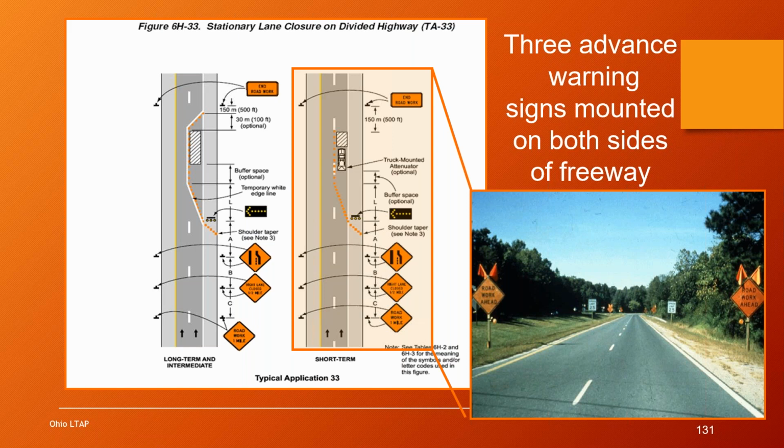roadway. And that's important in this situation because, well, one reason is you can think about heavy truck traffic. If a regular sized car is in the left lane and there's a whole string of semi trucks in the right lane, they may not see all the signs that are on the right side of the road. So with heavy volume traffic and high speed, we have the room for signs. So it's required in this situation that we put the signs up on both sides of the roadway, so you can see that on the left side of the slide there.